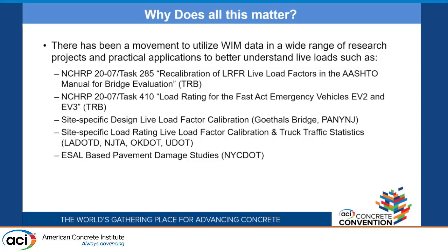We want to make sure it's designed to an appropriate load level. So we'll do a site-specific WIM analysis, collect all that data, use a probabilistic method to determine the probability of having multiple heavy trucks on the bridge at the same time, and come up with that custom load. So we've done that for Gothals Bridge, for the Port Authority of New York and New Jersey. We've done it for Louisiana DOT, New Jersey Turnpike, Oklahoma DOT, UDOT, et cetera, and also for the pavement side, equivalent single axle loads for pavement damage studies for New York City DOT.